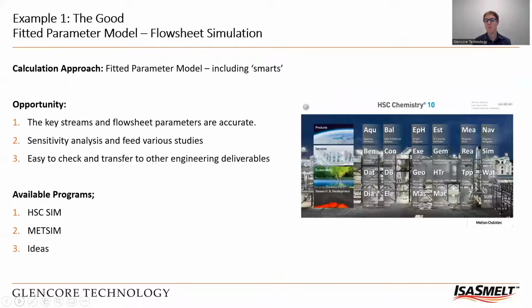Instead, what we have is these automated packages. So things like HSC Chemistry, HSC Sim, MetSim, SysCAD, Ideas, LIM. There's dozens of programs out there. So these take a while to learn how the packages work, but they're really good because they provide a graphic user interface and a lot of the background information, background calculations, all the material flows in and out, all those sorts of formulae are already pre-programmed into these packages. And you just need to put in the core information required to get your simulation going, all the sort of basic control loops and things there. All the thermodynamic information has already been checked and input into their databases.